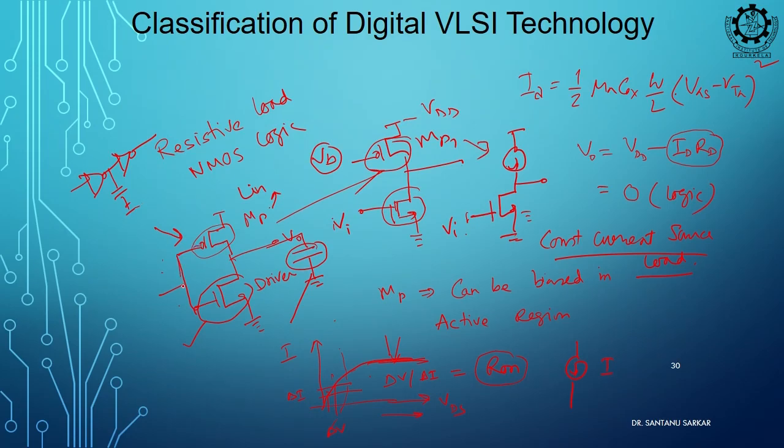This is connected to the gate, and a gate is nothing but an oxide cap, COX. So, your capacitance will be COX times W times L and its modifications. Any digital logic is actually driving some capacitance. So, load is always capacitance, be it static, be it dynamic.